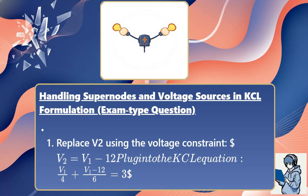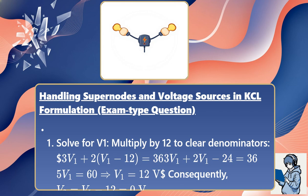Step 4: replace V2 using the voltage constraint. V2 equals V1 minus 12. Plug into the KCL equation. V1 over 4 plus (V1 minus 12) over 6 equals 3. Step 5: solve for V1.